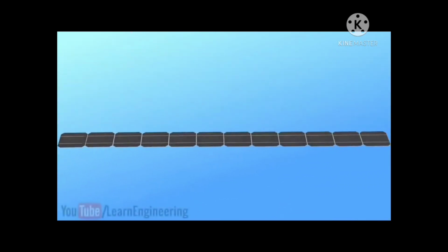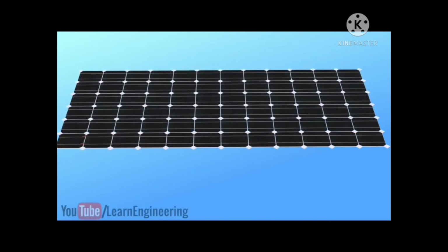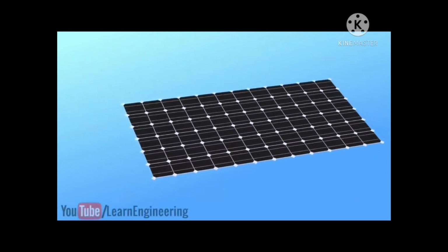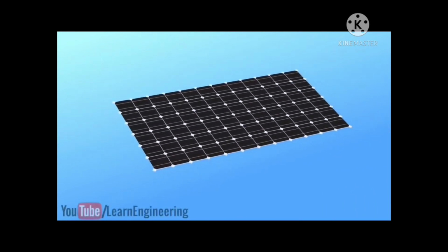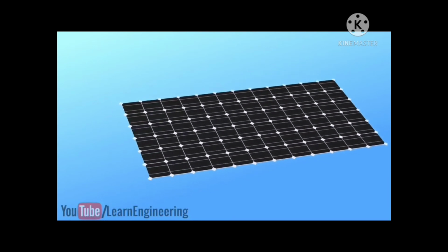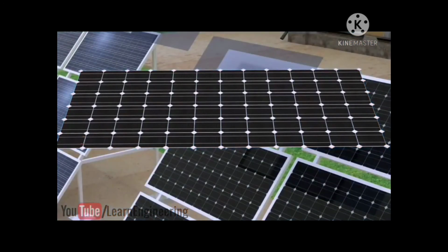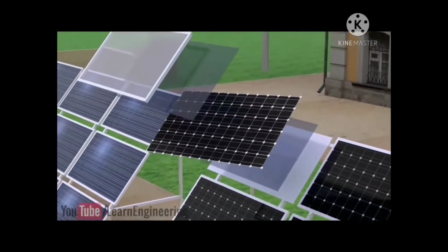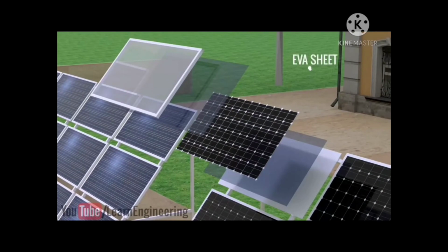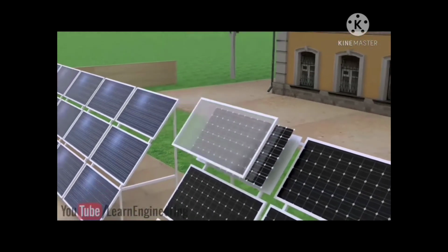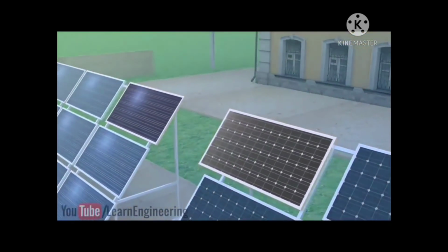When you connect these series-connected cells in parallel to another cell series, you get the solar panel. A single PV cell produces only around 0.5 volts. The combination of series and parallel connection of the cells increases the current and voltage values to a usable range. The layer of EVA sheeting on both sides of the cells is to protect them from shocks, vibrations, humidity, and dirt. Why are there two different kinds of appearances for the solar panels?